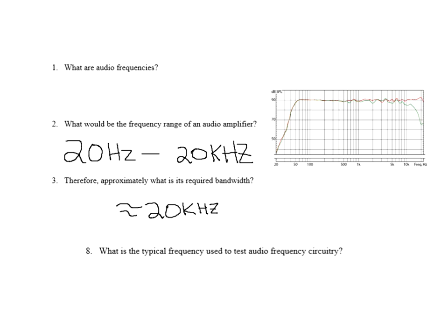Well, if I look at this closely, it's a frequency response curve. You should recognize it as such from second quarter. Here are the lower frequencies. There's the lowest cutoff frequency down around 50. Here is your upper cutoff frequency. It looks like it's around 20 kilohertz up here. So when you see a picture of this on the test, you're going to identify it as being audio frequencies. It's around 20 to 20 kilohertz there. You can see the frequencies down here.